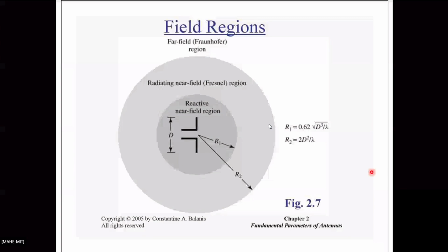So what are radiation patterns? Where do we see them? In the far field region, far away points, not in the near field region. The pattern shape is independent of R, and at a far away point the E_R component will be 0 usually, or very insignificant. E theta and the electric field lines will be transverse. The direction of propagation of the power is in the R direction.